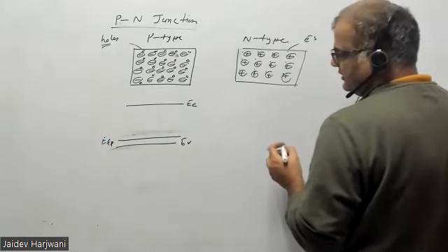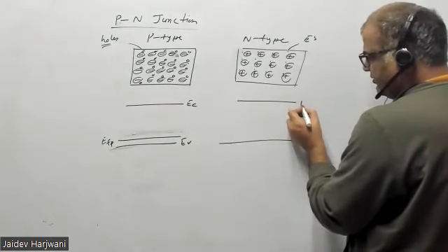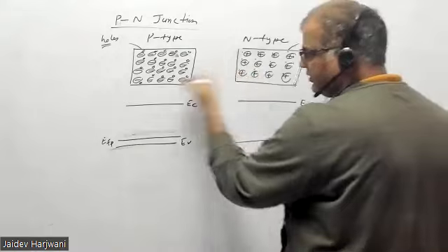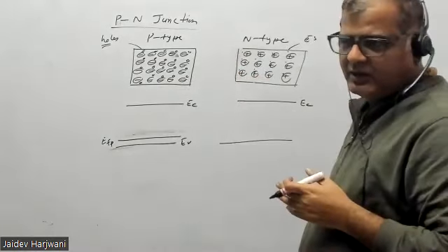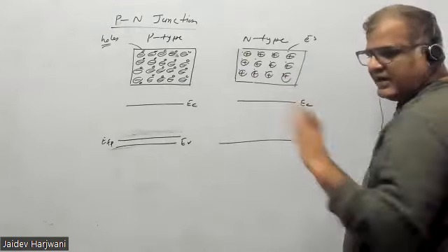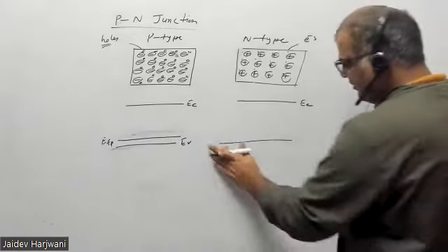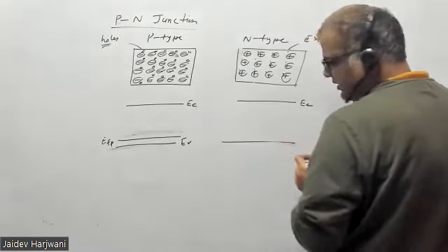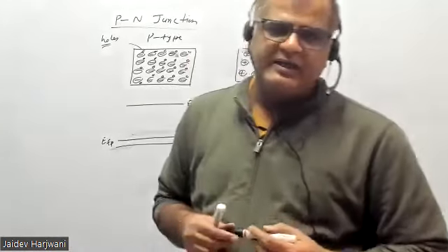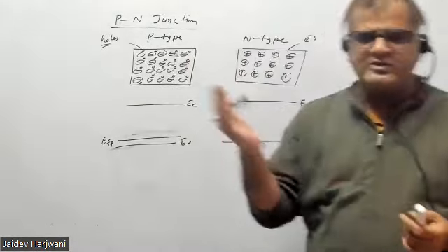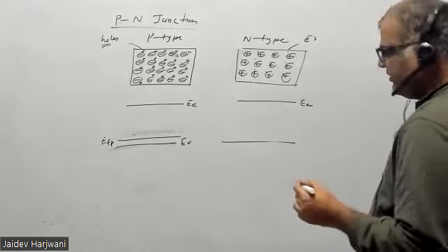And here, say, this is my n-type material. Now the material is the same. It is silicon, and you are doping something into the silicon. So the energy band diagram will not be affected much by impurities, because you are putting in very little impurity. The remaining section of the material is the same, so why should the band gap change? The band gap is almost the same. Only the position of the Fermi level is shifting.